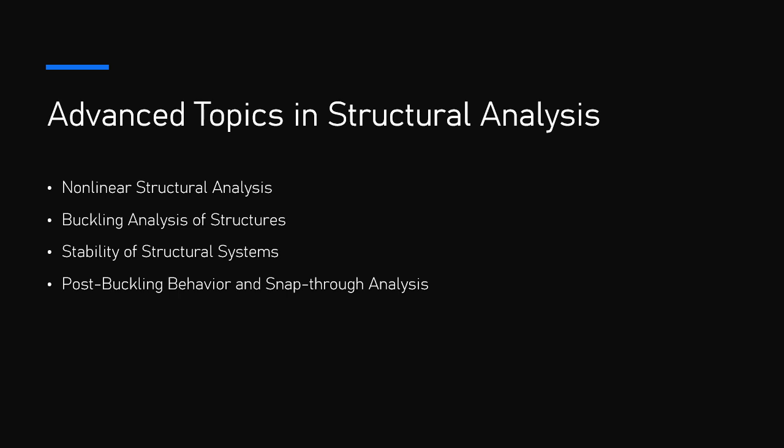In this case, the local deformation leads to instability in the member, even though the overall structure might remain stable. An example is the local buckling of plates in a steel column under compressive load, where the plate itself buckles, leading to a decrease in the load-bearing capacity of the section. 5. Torsional buckling.